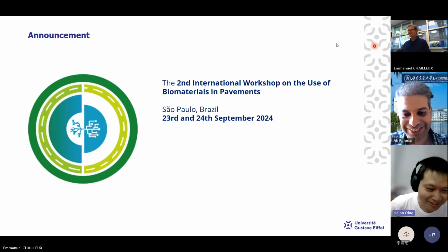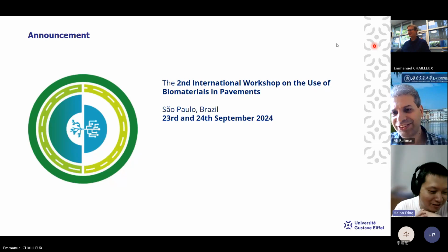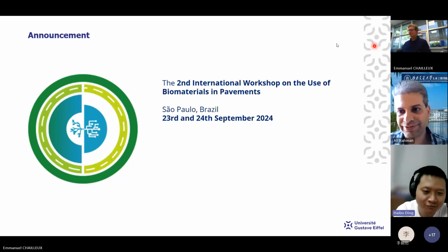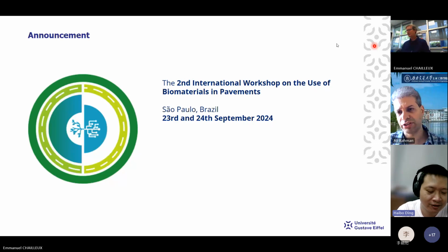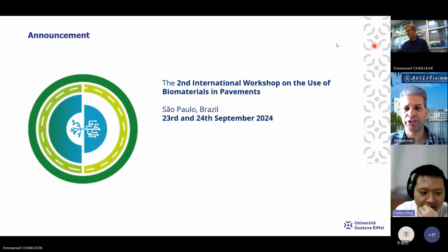Okay. Thank you, Professor Emmanuel. Very good presentation. I have one simple question. For your DSR, you did the DSR at -10, if I remember, the temperature is -10. So did you use a 4mm plate, or just a regular 8mm?